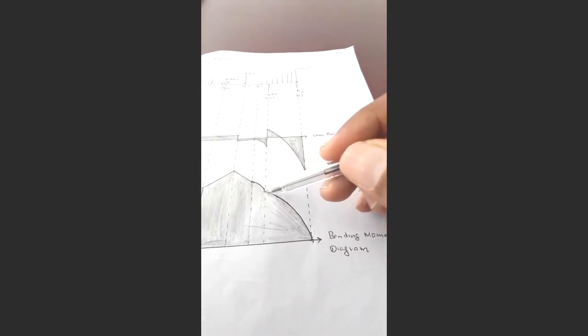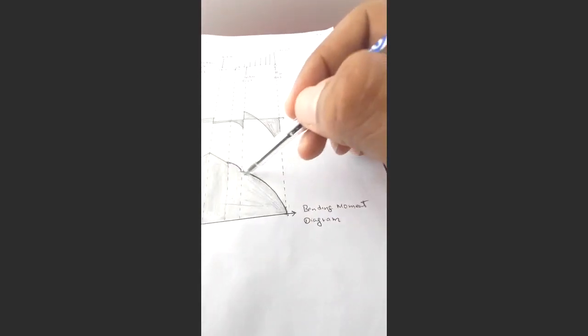So you have to connect this. The connection must definitely be made by an increasing type of curve, because the load intensity is increasing, right? Also look at the curve type: 13 times x minus 1 plus 60. Because of this part, it has become a third degree curve, x minus 5 cube. So this is how you are going to connect it, with an increasing type of curve. This is how you are going to sketch the shear force and bending moment diagram, right?